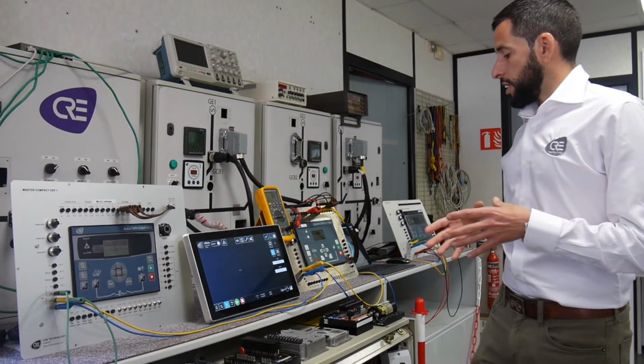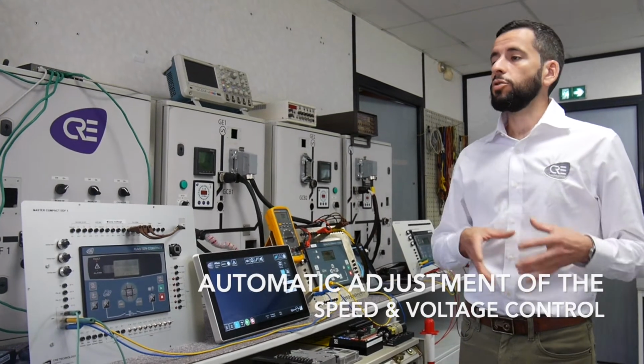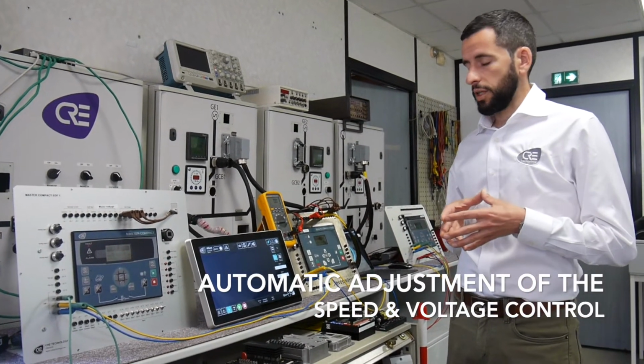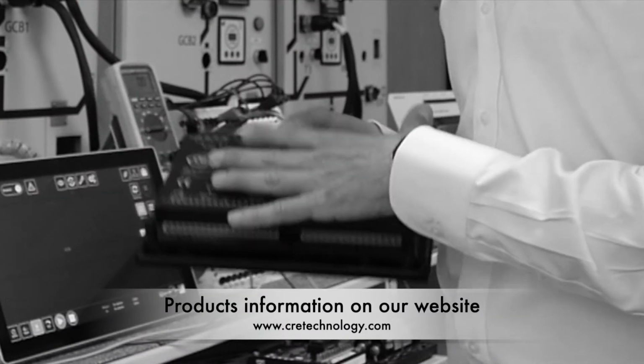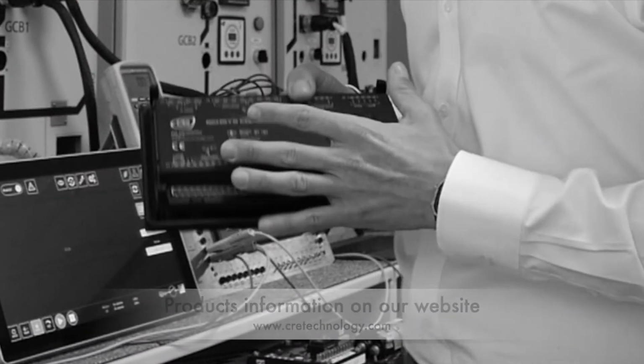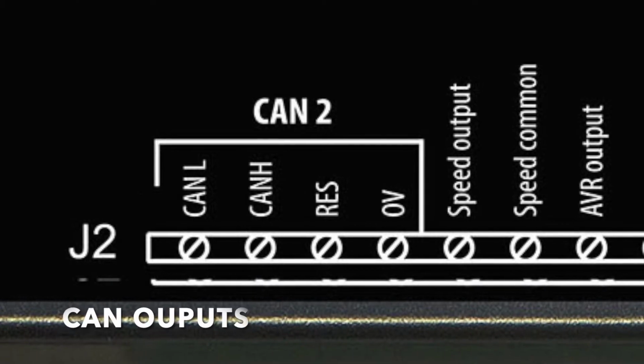So now about the prerequisites of the EasyCalib feature. As I said, this is made to automatically adjust the speed control and the voltage control of your genset. How does this work? You will have your Genesis Compact Prime or Genesis Compact Mains, or your compact paralleling controller from CRE Technology. This controller will have a speed control output and a voltage control output.